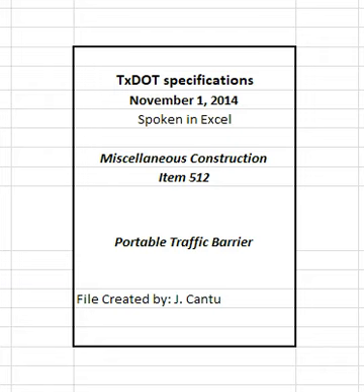Remove formwork after the concrete has reached sufficient strength to prevent physical damage to the member. Move barrier sections to a storage area and place them on blocking to prevent damage when they have attained sufficient strength to permit handling without causing visible damage. Produce precast barrier to the tolerances given in Table 1 unless otherwise shown on the plans.